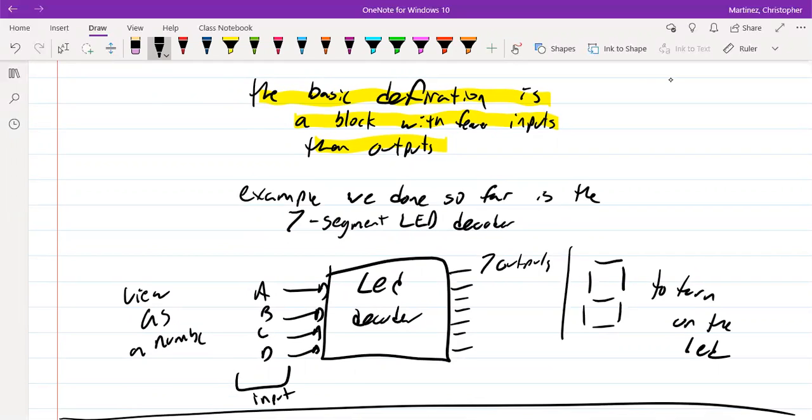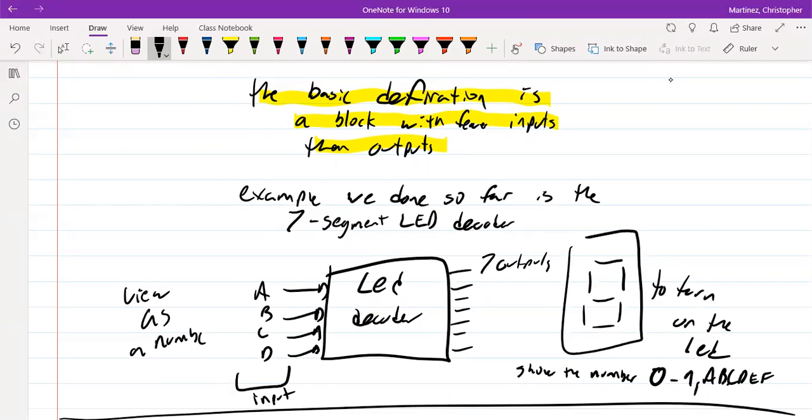On our little display, we had a 7-segment LED, and we wanted to show the numbers 0 through 9, and then A, B, C, D, E, F. They get the full 16 combinations. Here we had 4 inputs being mapped into 7 outputs. This gives us the idea of a decoder: for any given value of input, there is one value of the output.